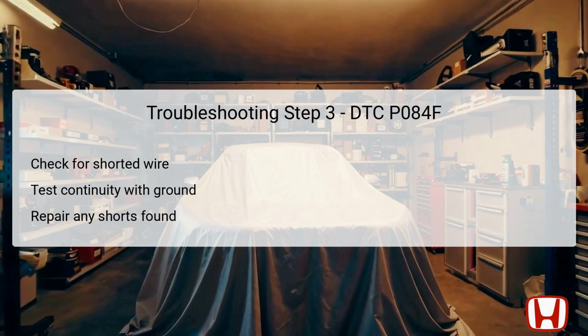If no continuity is found, then the wiring is considered intact, and further diagnosis should involve consulting authorized service information or possibly substituting the TCM with a known good unit for testing purposes.